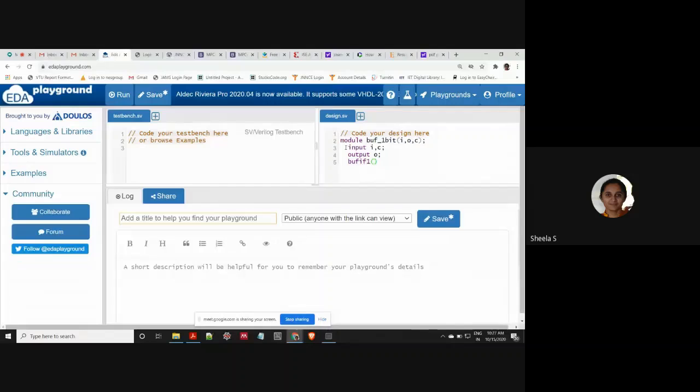It indicates that I am considering the control logic as 1. Whenever the control logic is equal to 1, it will activate the buffer. According to the syntax, first we write the output, then the input, and last the control. This is the general syntax for bufif, and next let us write endmodule.